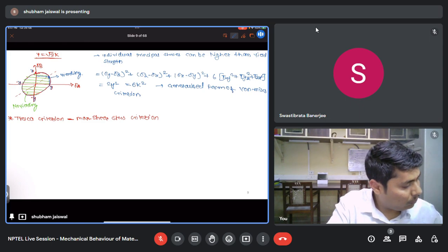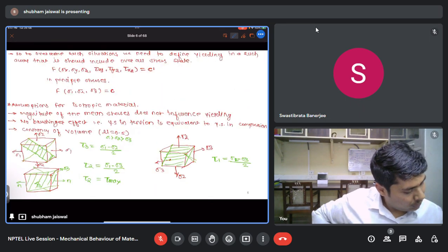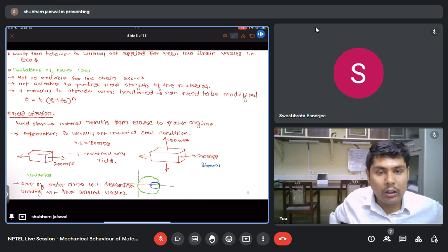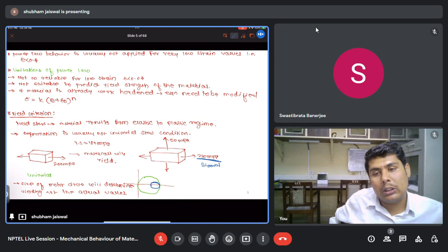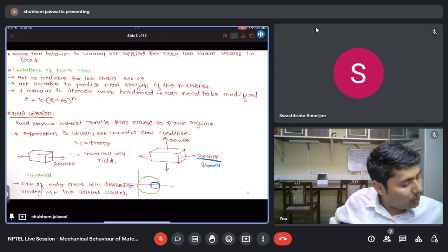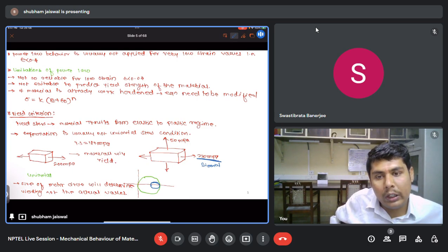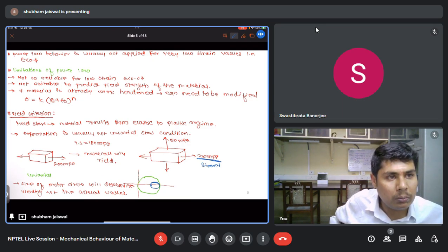In the very beginning I discussed, in this equation, you can see it is 220 and this is 50 megapascal. This 220 is greater than 180 megapascal, is it not? But if you see the Mohr circle, the shear stress that is coming is very less. It is very less than the yield strength of the material. So the material will not deform.